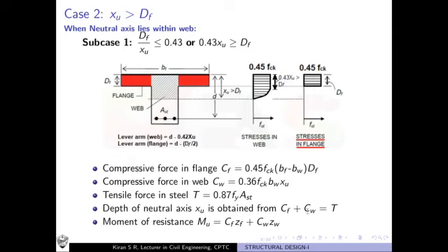Okay. Now, how do you find the moment of resistance here? Unlike the previous cases, we have divided the T-beam into two parts. One is a flange part and second is the web portion. The flange portion is also contributing to moment resistance, and the web portion is also contributing towards moment resistance. So the moment resisted by flange as well as web you have to find out.